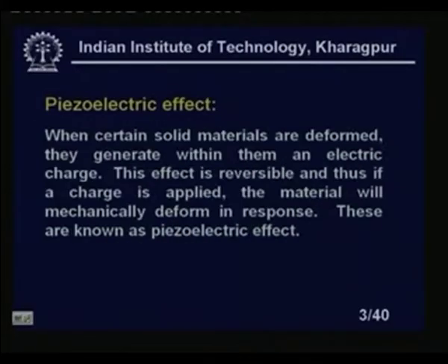What is the piezoelectric effect? When certain solid materials are deformed, they generate within them an electric charge. This effect is reversible, and thus if a charge is applied, the material will mechanically deform in response. Exactly this we did while making the ultrasonic sensors. Instead of steady voltages, we give a time varying voltage across one plate. Obviously, the force you get is also a time varying signal, which can be in the megahertz range, so we can get ultrasonic signals from these piezoelectric sensors.